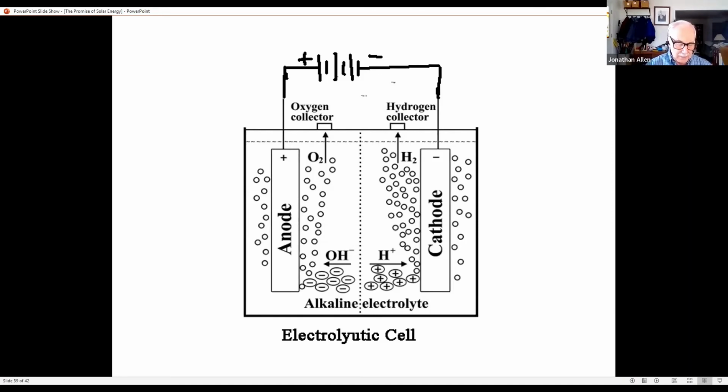There are now experiments with reversible cells where the same device can work both as the electrolyzer and the fuel cell. Hydrogen energy storage has a very dedicated fan club. Storing electric power, however, the electrolytic hydrogen has lousy round-trip efficiency. Electrolyzers can run about 70% efficient, and the best fuel cells about 60. Figure another 10% lost compressing the gas, and you get back about 38%. If instead we recover the energy by burning the hydrogen in an Otto cycle gas engine, we get about 20% efficiency.